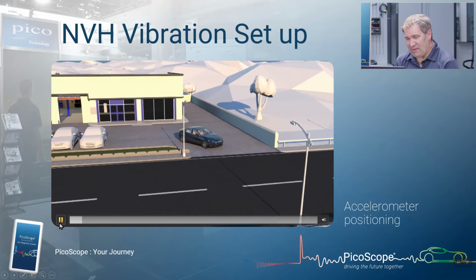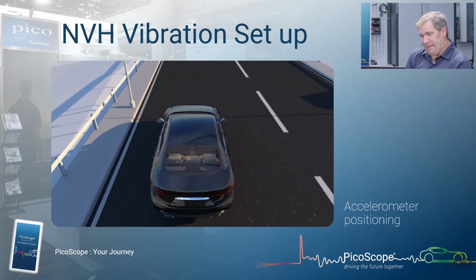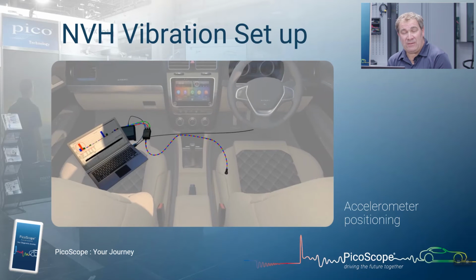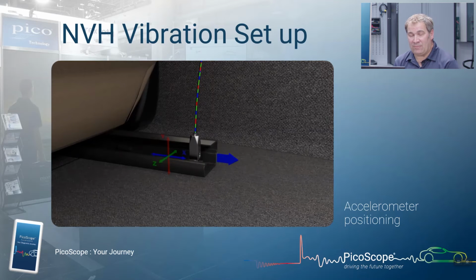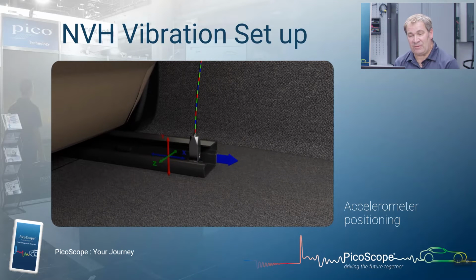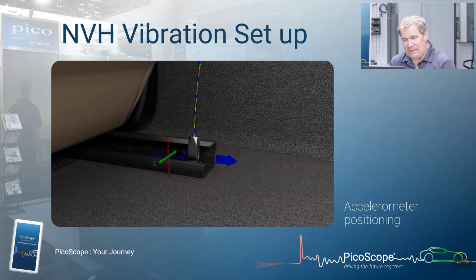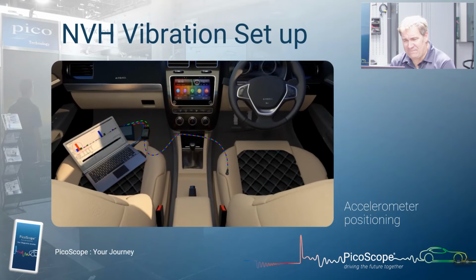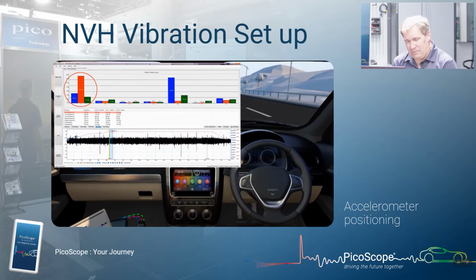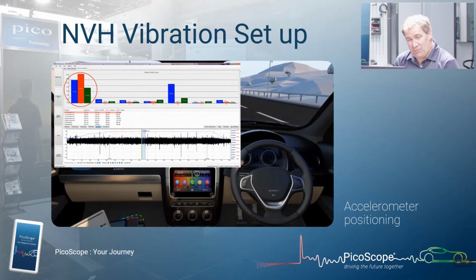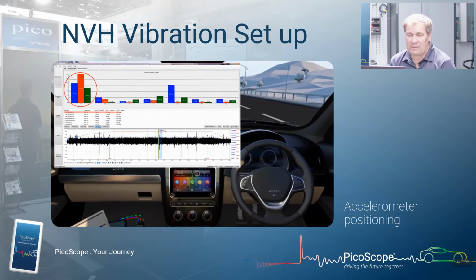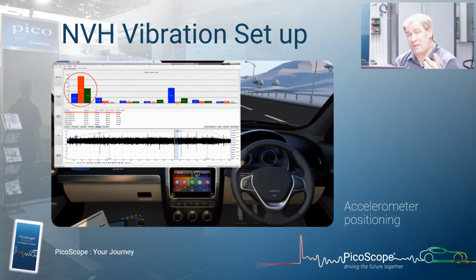So here's our road test. And as Steve said, we assume that the first person who starts to feel or hear a vibration, who is sensitive to a vibration, is going to be the driver. So we tend to use the seat support as our first measurement. And you will start to see there, we've got our 3 bar graphs, we've highlighted it there. So remember those 3 colours.